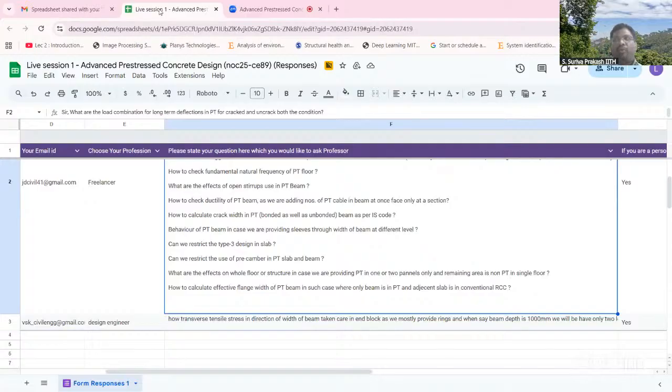But I would say, because your screed slab itself, especially when you go for a PT system, you also put a screed slab to connect everything together, right? The screed itself is 50, 60 mm. Then if you have a camber of 50 mm, imagine your screed will become almost 100 millimeter. Then you add significant weight, which will become counterproductive. So that's why we have to be careful. Sometimes in beams, at localized locations, probably yes, but there also we have to be careful. Exactly what is the maximum that we can allow?